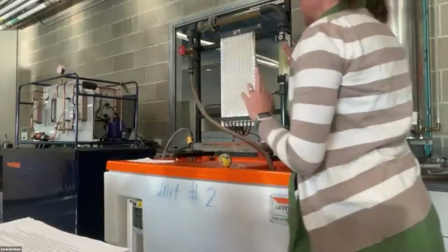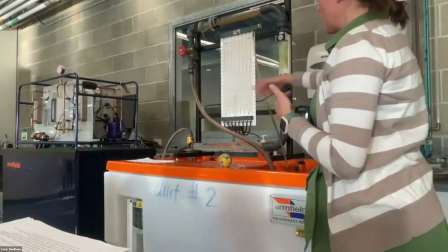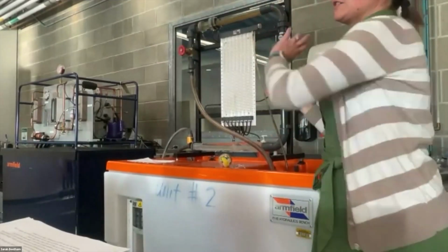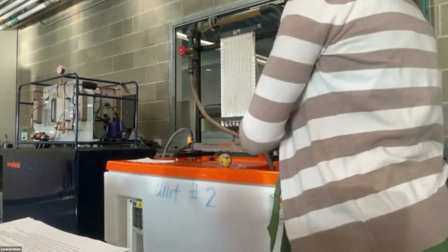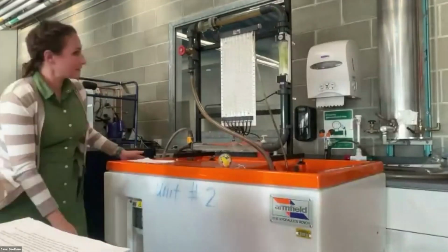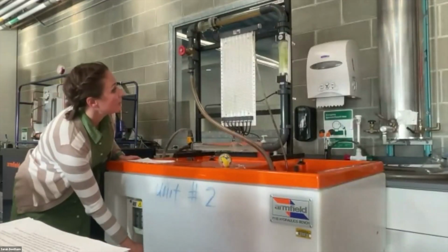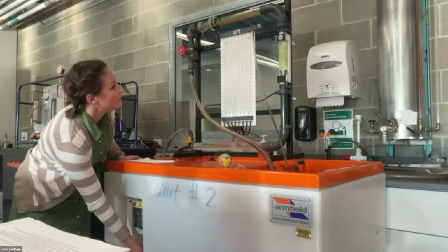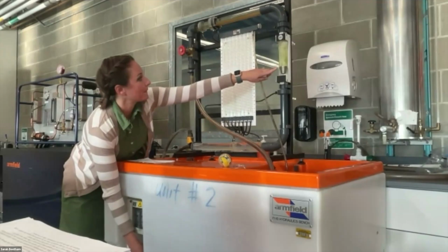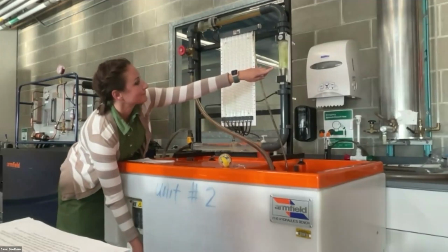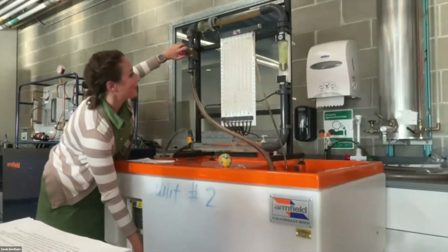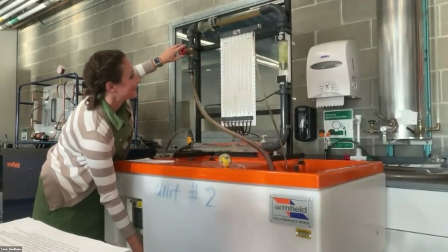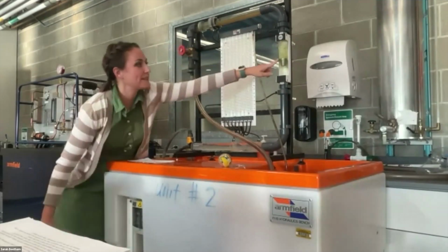And then if you ever get yourself into a position of the barometers being overflowing, just start from the beginning. Close all the valves, turn it off, start again. That's completely fine. So what we're going to do next is I'm going to increase very slowly the flow rate. And I'm going to be watching this gauge here. I've already done it. So you can see this little weight in here.